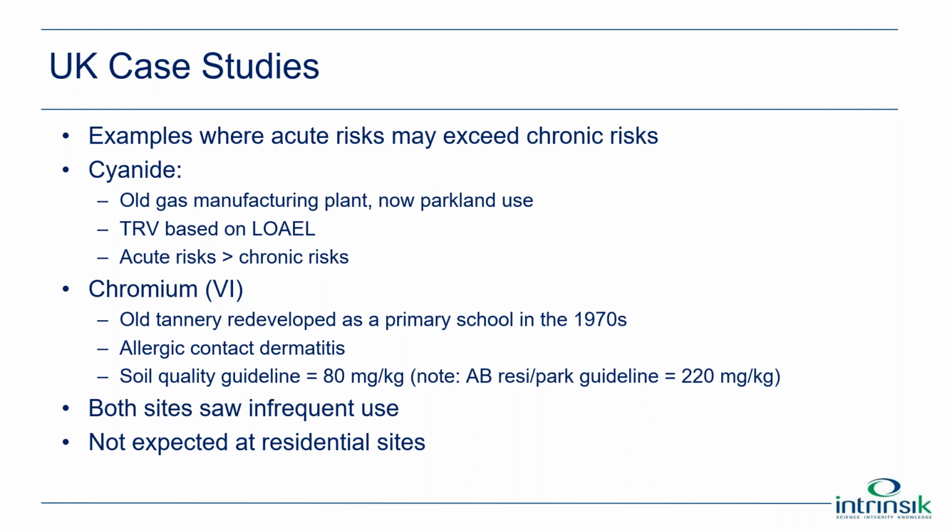The other example is for chromium-6, and this is an old tannery site that was redeveloped as a school in the 1970s. Same kind of idea. This had been capped, but over time that cap had eroded, and some of the contamination had come to surface. And we know that on an acute, short-term basis, chromium can actually be a pretty potent skin sensitizing agent, so it could cause allergic contact dermatitis.